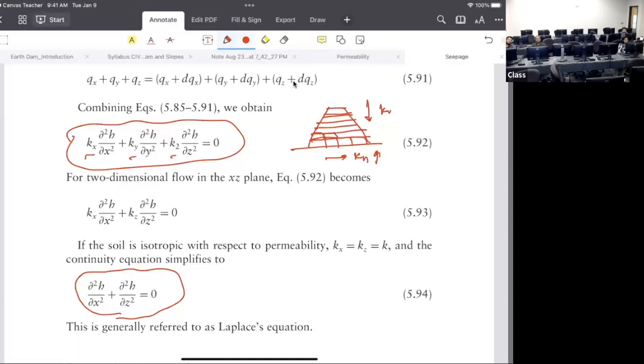So you have an anisotropy, but this anisotropy gets flipped. In clay, or fine-grained material, there is usually the anisotropy because this is how it's constructed, layer by layer, right? When there is desiccation, very good, in the expansive soil, your Kv is higher than Kh. Correct.